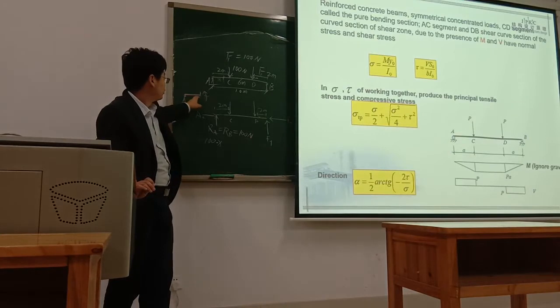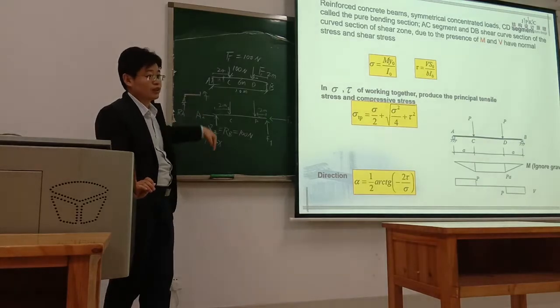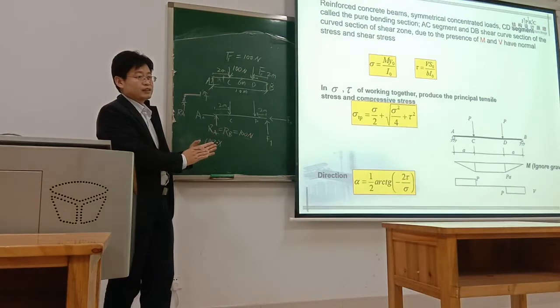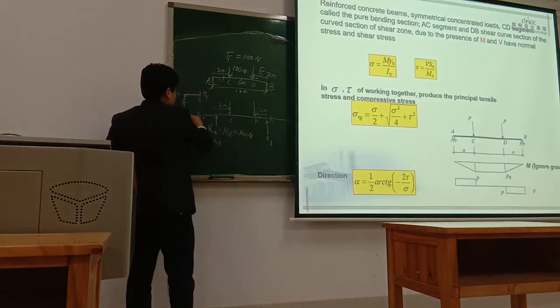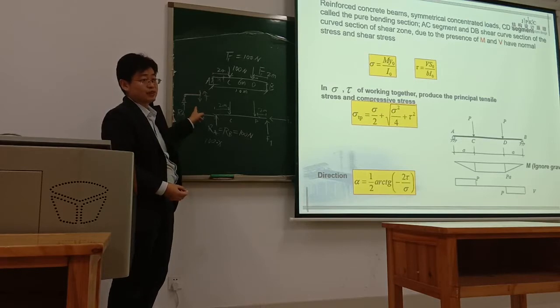To balance this part, we need another force going down. So at the cut section, this downward force is the shear force.